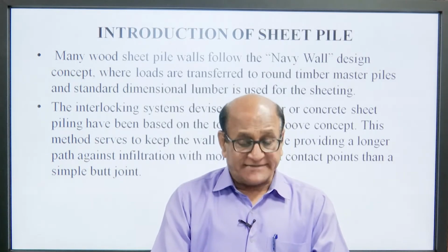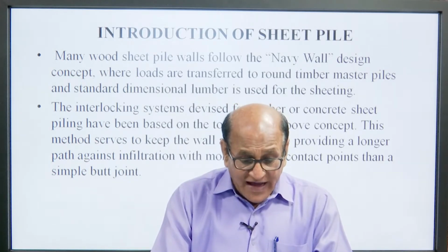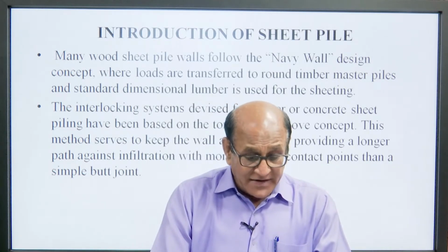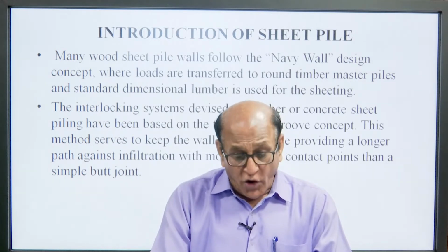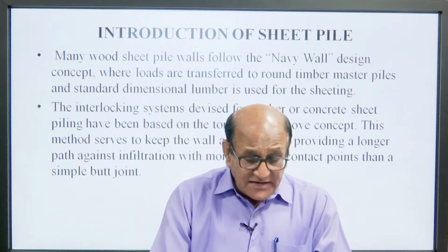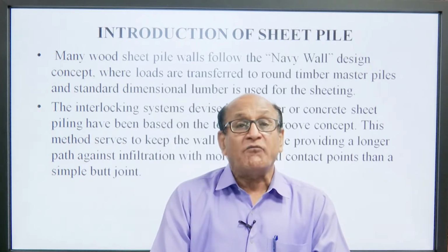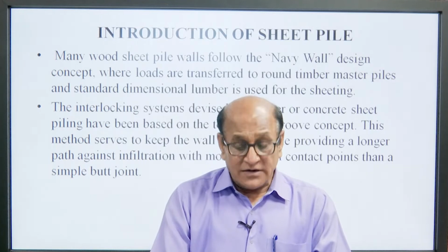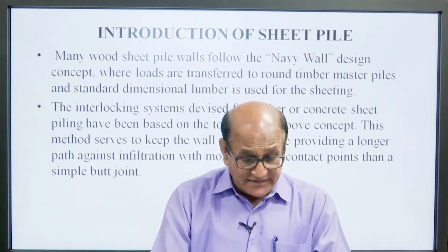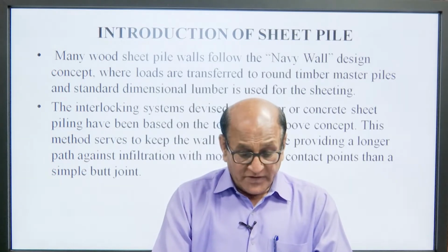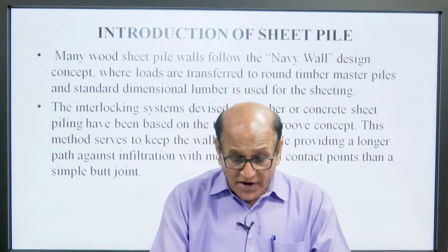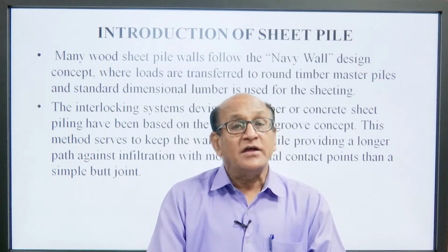The interlocking system devised for timber or concrete sheet piling is based on the tongue and groove concept. This method serves to keep the wall aligned while providing a longer path against infiltration with more potential contact points than a simple butt joint.